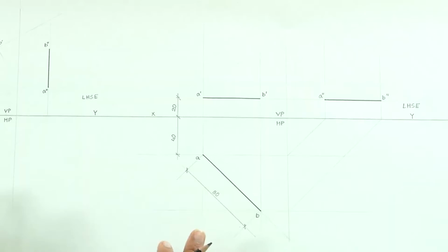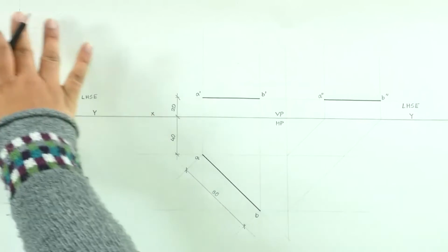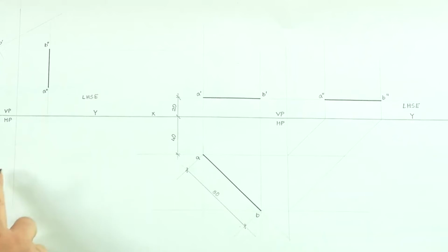So, the point is not just about the technical correctness, but it is also about how you make your sheets look better. Another word of caution is, I am familiar with how to draw, so I can directly darken the lines here. Do not copy me here. You should always make the entire drawing in very light, almost as dark as the projection lines, and then gradually start darkening it from light to dark. The darkest lines should be drawn in the last, so that they do not smudge.